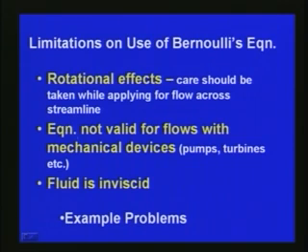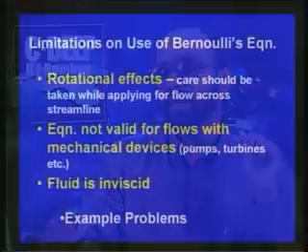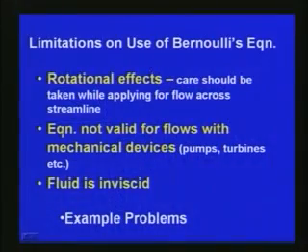Other limitations include that Bernoulli's equation is not valid for flows with mechanical devices. For example, in a pipeline system when we are considering a problem with pumps, turbines, etc., special care should be taken so that Bernoulli's equation can be applied.